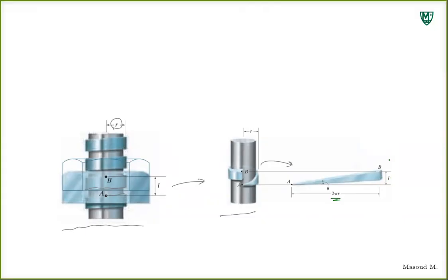Now, this is known as lead, right? Basically, the lead of a screw is the distance the screw advances in one turn. So when you turn the screw once, how much the screw moves up or moves down, or better to say advances, because it can be in any direction. In this case, how much it goes up or down. That L is called lead.